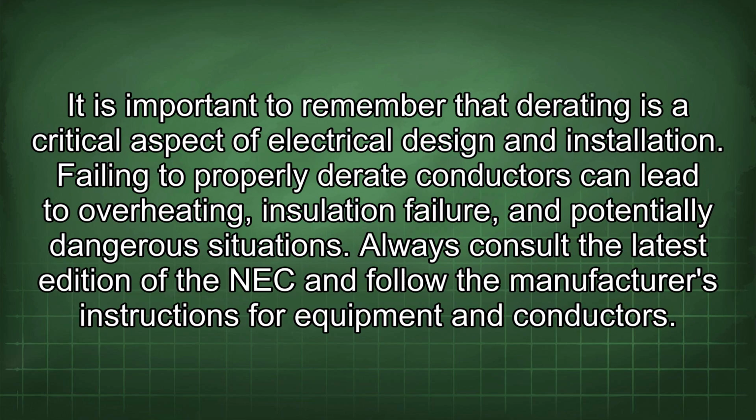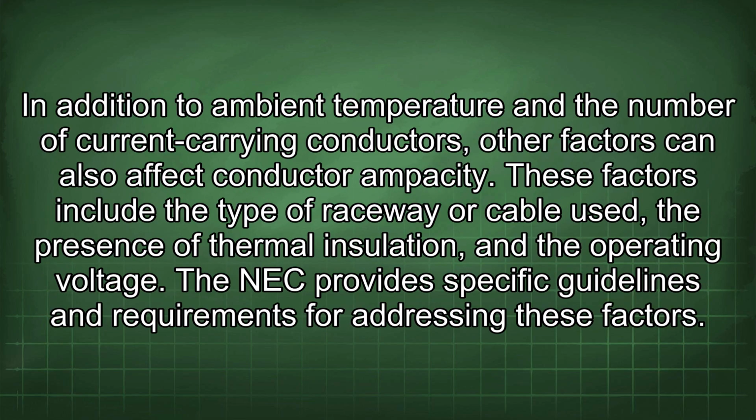It is important to remember that derating is a critical aspect of electrical design and installation. Failing to properly derate conductors can lead to overheating, insulation failure, and potentially dangerous situations. Always consult the latest edition of the NEC and follow the manufacturer's instructions for equipment and conductors. In addition to ambient temperature and the number of current-carrying conductors, other factors can also affect conductor ampacity. These factors include the type of raceway or cable used, the presence of thermal insulation, and the operating voltage. The NEC provides specific guidelines and requirements for addressing these factors.